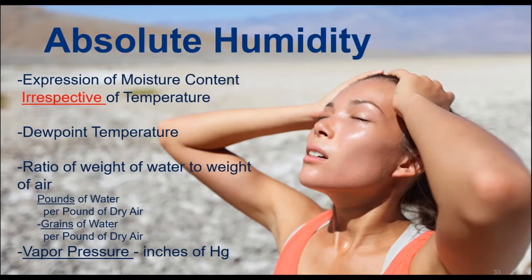Let's move on to talk about the absolute humidity measurements. These are going to be irrespective of temperature. We want to have an expression of moisture content irrespective of temperature. The three we're looking at today: dew point, number one; the ratio of weight of water to the weight of the air; and then vapor pressure in inches of mercury. Three measurements of absolute humidity.